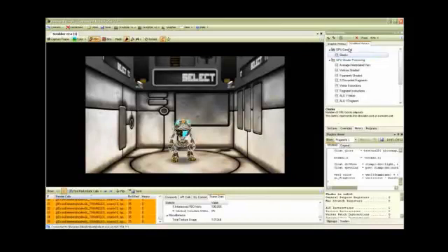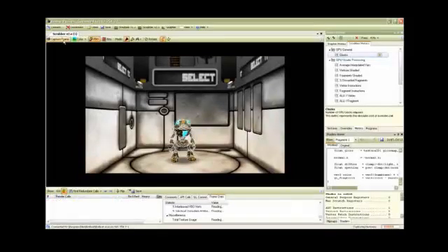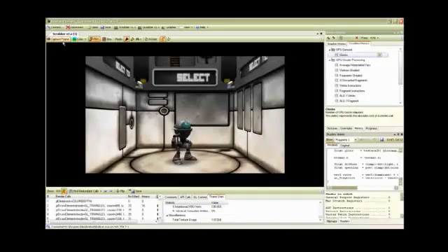To sample this metric, I can just grab it and drag it onto the scene. And now what I need to do is recapture that frame. So I'll go ahead and do that. And what this is doing is now, as all those draw calls are being made, it tells the GPU to track that particular metric and see what the cost of that particular draw call was. So this adds a new column now to the call trace that shows you that clocks metric. And you can see that visually here.